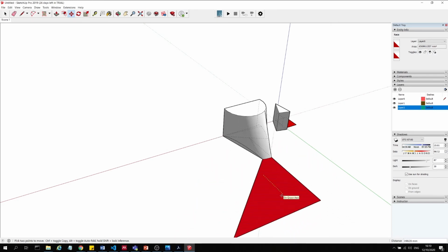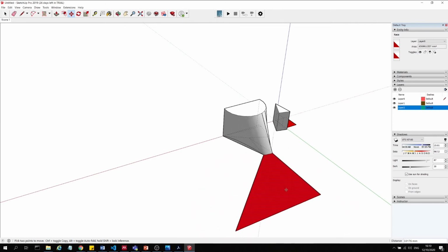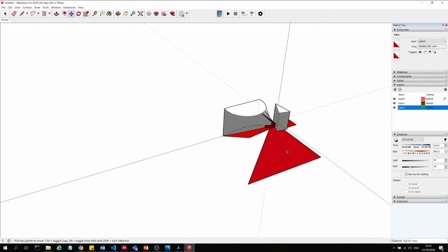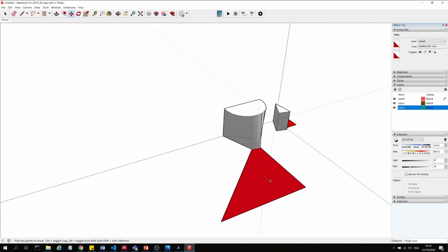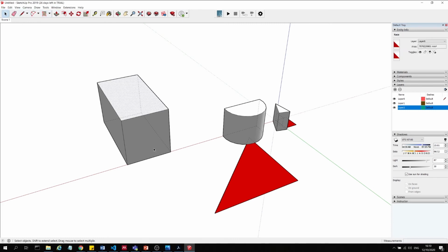of the SketchUp peculiarities. So basically, if any 2 lines touch in SketchUp, SketchUp will already think they are related, and then if you select one surface and move it around, it will affect your whole geometry. So to illustrate this, all I want to do is just draw a simple rectangle like this, and then extrude it like this. Now, with my selection tool, I can select a single face, I can select an edge, or I can select the whole volume.